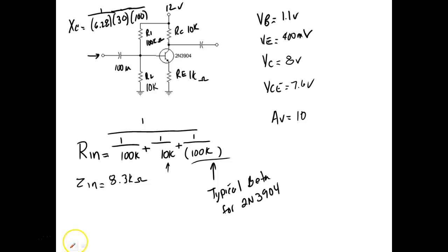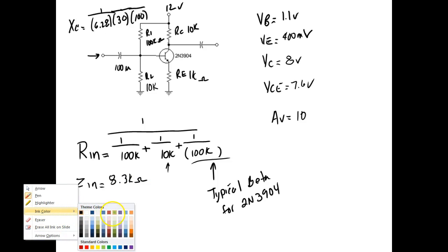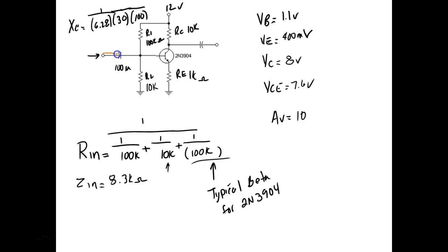So this is the path that the signal takes, and you can see it. It comes flying in here, right? We looked at this. It goes up to that guy. An AC source sees a DC battery as 0 ohms, guys. Then it goes this way, and then it goes that way. Are we okay?